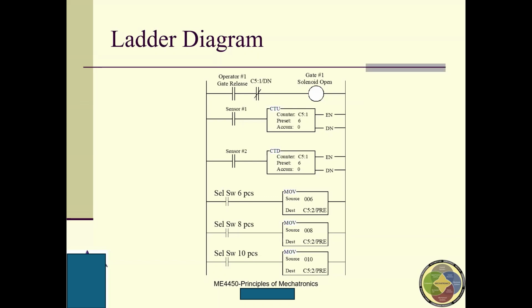Okay. It will trigger the CTU, and the CTU goes up, and then the ACC goes 0, 1, 2, 3, 4, 5, 6. Until this goes to 6, the done bit is set. If the done bit is set, then the opposite is false. As a result, this solenoid is turned off. The solenoid is controlling this conveyor belt. The conveyor belt will stay there.